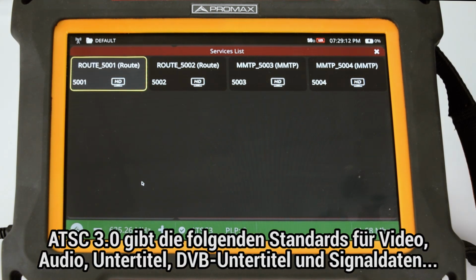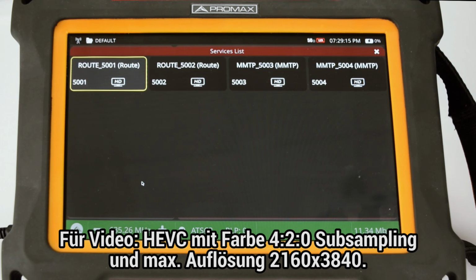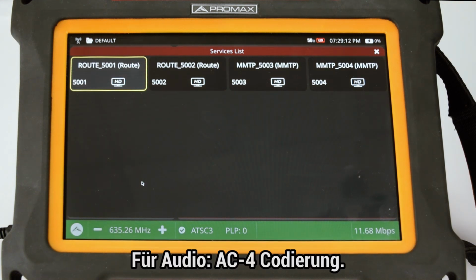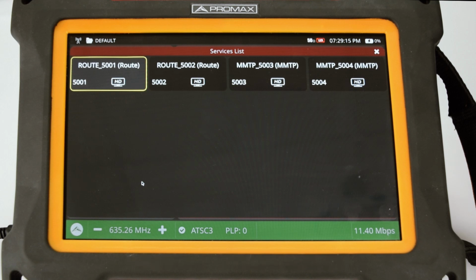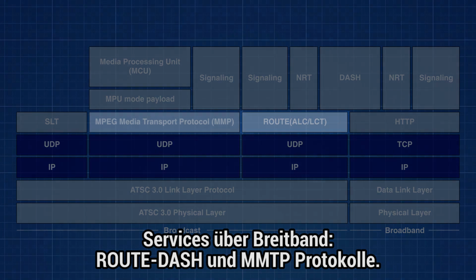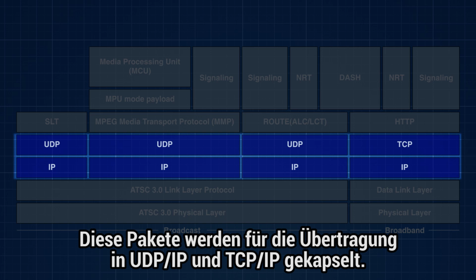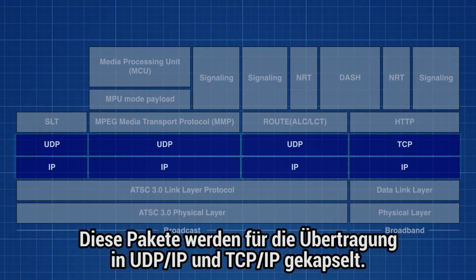ATSC 3.0 specifies the use of the following standards for the encoding of video, audio, subtitles, caption information and signaling data. For video, HEVC encoding is used, with a color subsampling of 4:2:0 and a maximum spatial resolution of 2160 by 3840 pixels. And for audio, AC-4 encoding is used. Service delivery over broadband makes use of ROUTE/DASH and MMTP protocols. These packets are then encapsulated into UDP/IP and TCP/IP packets for their transport.